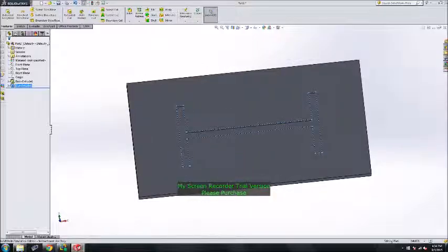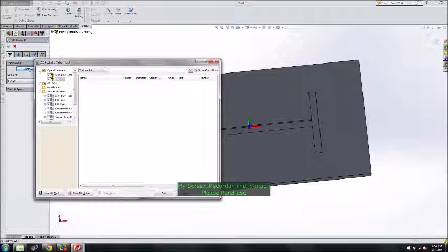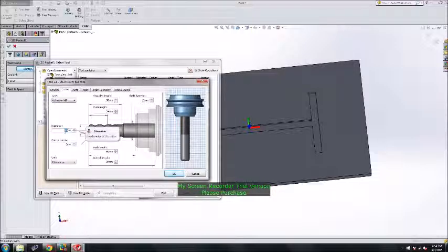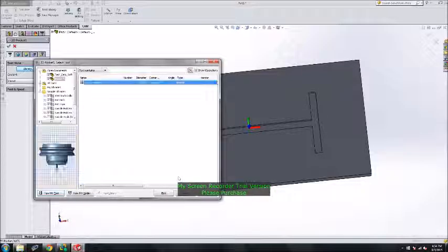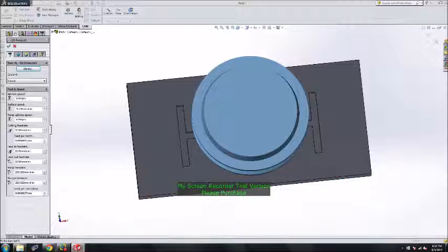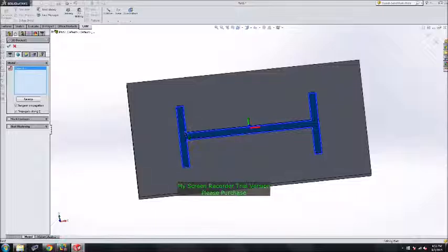Now select CAM, 2D milling, since it's a pocket, so 2D pocket again. Select your tool. Since no tool is selected, you define the tool. Your tool has 1.54 mm diameter and it's a flat mill. Sorry, it's a ball mill. Press OK. Select. Then select the face you want to etch. Here the face is selected. Press OK.